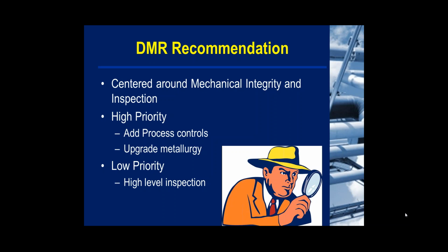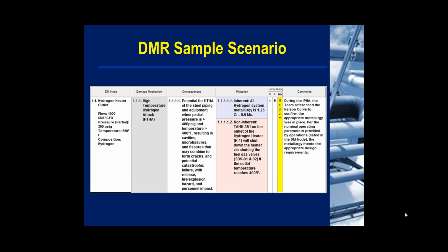Secondly, for safeguard development, we also want to focus on mechanical integrity depth. A lot of times in HAZOPs, we see that mechanical integrity is acknowledged, and it's said that, okay, well, we do PMs or we do mechanical integrity on a routine basis. But the idea here for the damage mechanism review is to go into a lot more depth on mechanical integrity, ask about the frequency, challenge the effectiveness of the PMs being applied, and how operational observation sees the piping and the metallurgy involved.